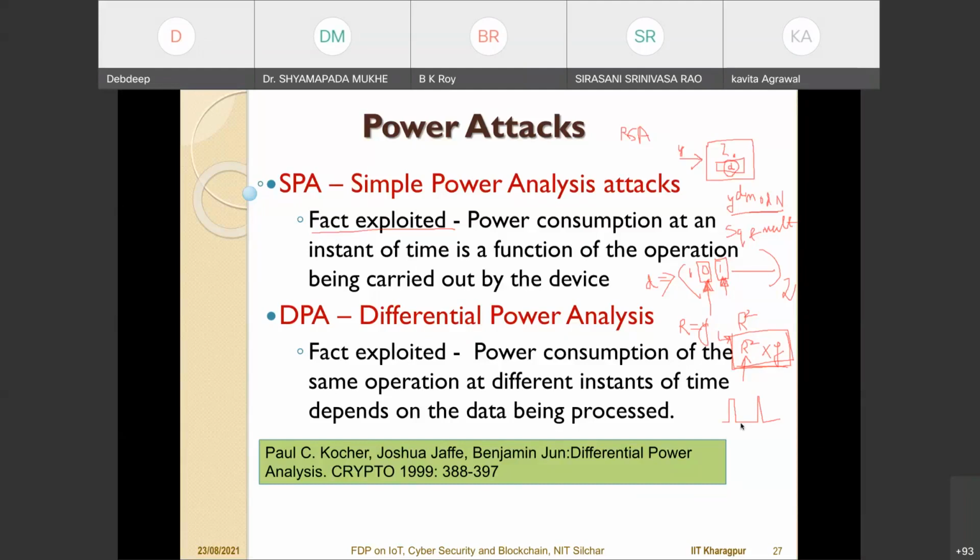So the power consumption is dependent upon the underlying operation, and if you implement exponentiation in the naive manner, which is not really naive because it is one of the most popular ways of implementing exponentiation, called square and multiply, it leaks. This is an optimization that you are doing to make your implementation more efficient, but the same optimization leads to the leakage of your secret key. So the question is, how do you ensure that your design will be efficient but still secured against such leakage sources?